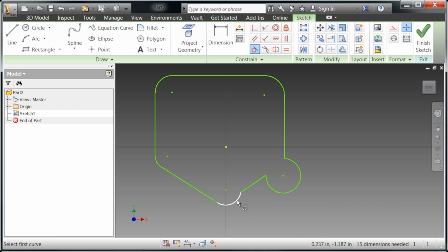Now as you can see, this is a pretty fast process and it works very similarly to how you're used to in Fusion. Now this part, actually, I want to adjust a little bit, because if I had added a tangent there, it wouldn't have ended up how I wanted it in the end. So I went back and modified it to where I wanted. Continue to lock down everything, adding equal constraints at the arcs. So these arcs are always going to be equal. Now we're going to do the same thing to the lines. The lines are going to be the same length. These constraints are pretty much the same constraints that we use within Fusion already.